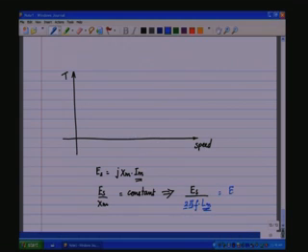So if we keep E stator by f constant, then the flux Im is a constant. So which means if the stator voltage is reduced, reduce the frequency also proportionally such that this is constant, then Im is a constant, then you can utilize the whole range of the torque.